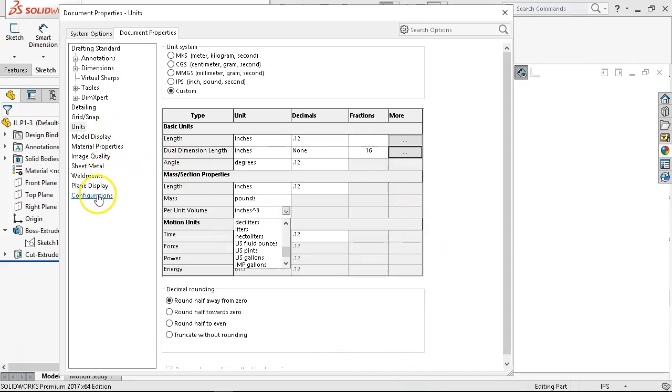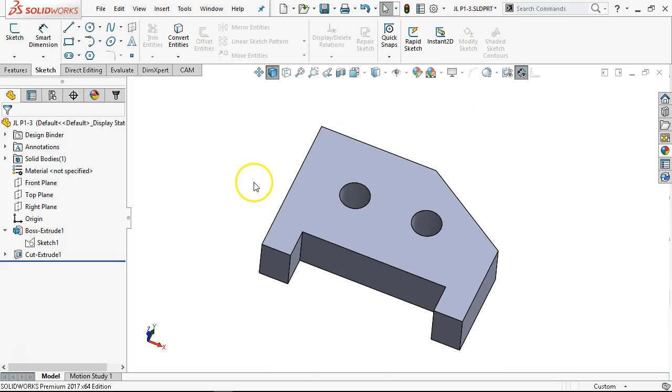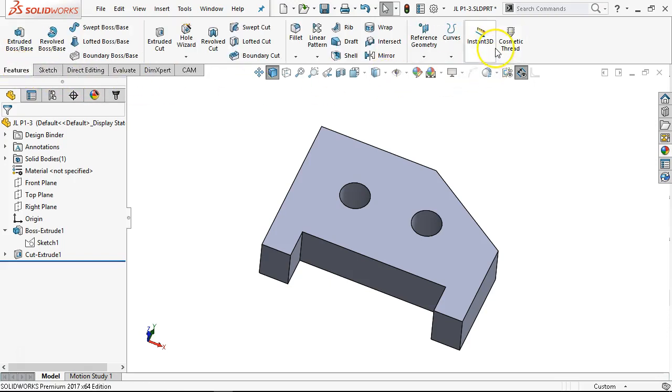Let's see, probably most of the rest of these are in the "we'll get to them" range. So just to close up with things that should be on and off in your features and sketches. Instant 2D, leave it off. Under features, Instant 3D, leave it off. The orbits and the things that it selects are nuisance items to me. They're not providing you any value.